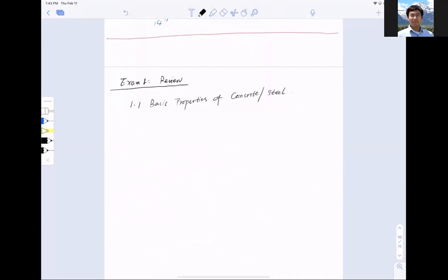steel, okay? And for concrete, what it looks like, we use a stress strain curve to represent or describe the behavior of concrete, right? Remember? And so for the compression side, it goes like this and drops and fails. For the tension side, it goes like this and drops and fails, okay? So we call this right here at the peak stress f prime c, okay? And then we call this Young's modulus of Ec, which is 57,000 square root f prime c, okay?